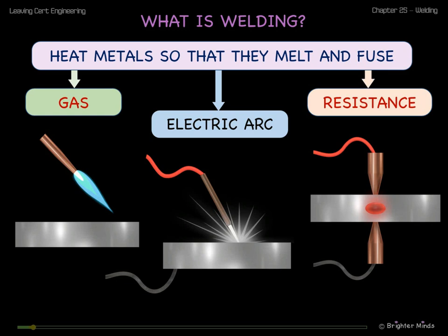Welding is normally used to join metals of the same type. It is difficult to weld metals of different types together because they can have different melting temperatures and they may not dissolve well in each other.